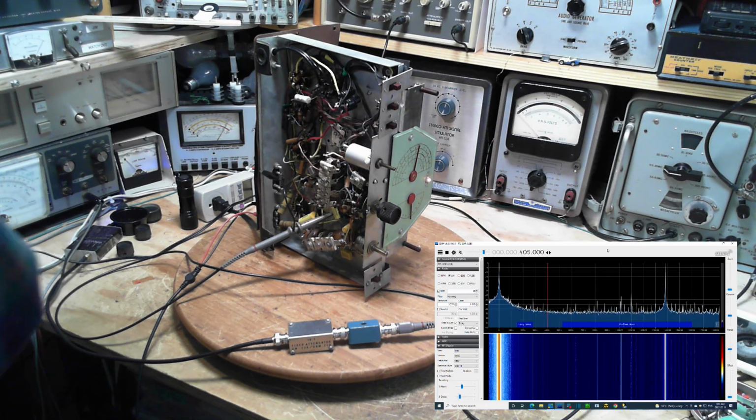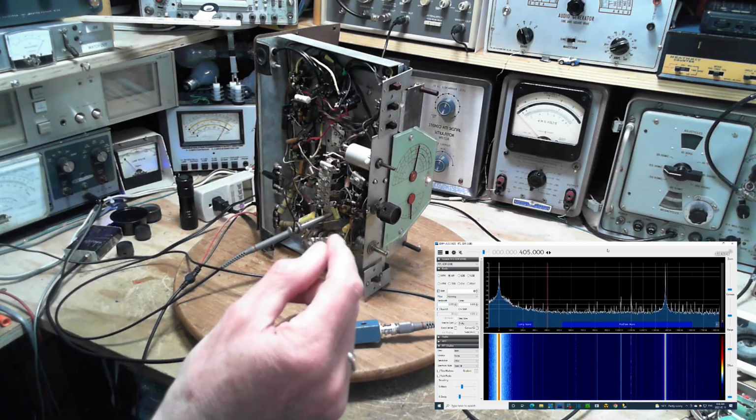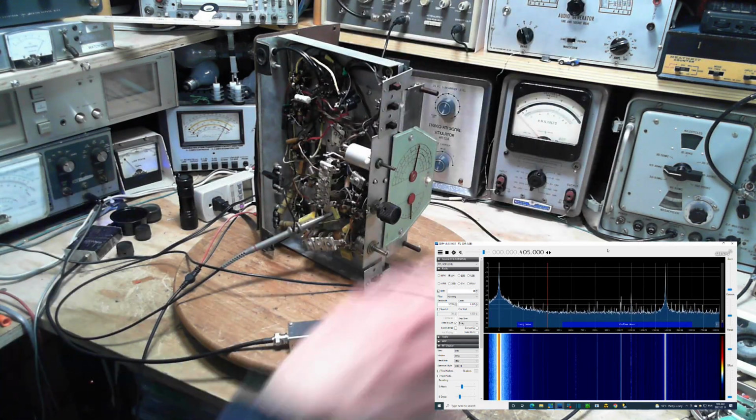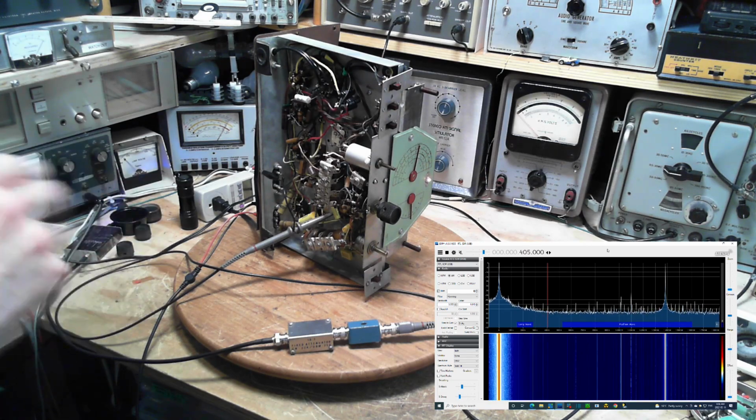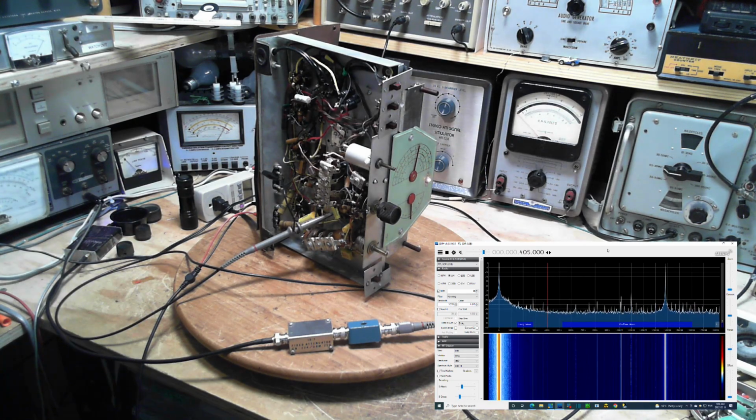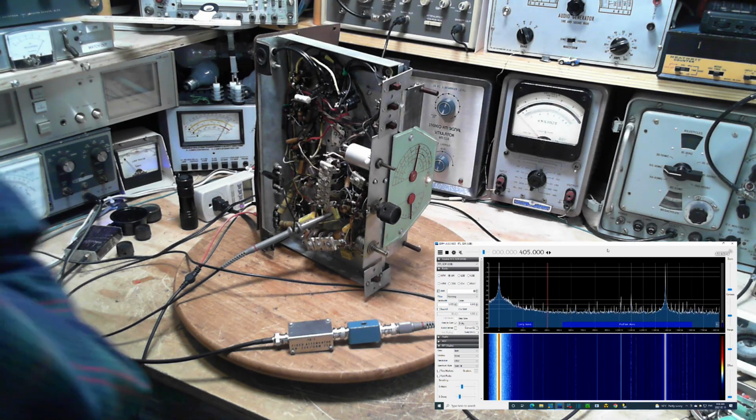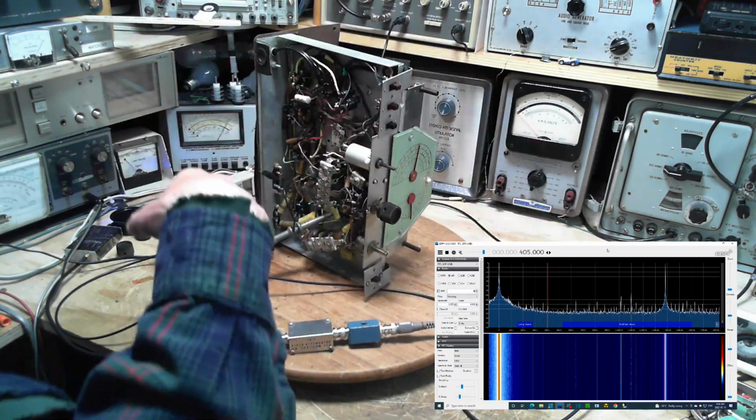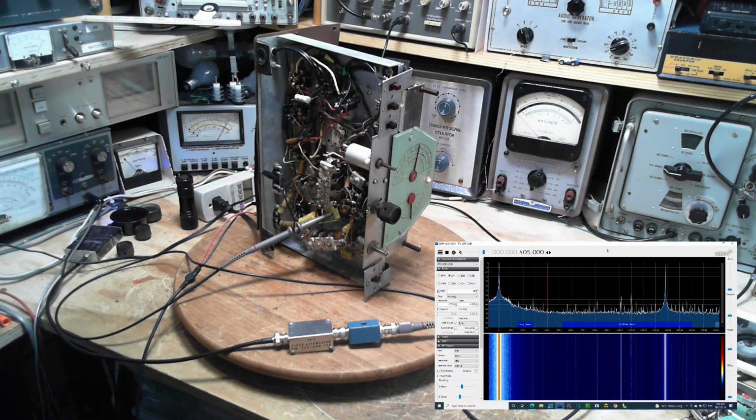It's an interesting question, because in my shortwave world, when I'm listening to radios, sometimes I have 2 or 3 radios running simultaneously, all on the same antenna. So if there are signals making it out of those radios and onto that antenna wire, it's going into all the other radios. It makes the scenario I'm looking at here just multiply it by the number of radios you've got going. Everybody hearing everybody. Now for sure you can hear local oscillators in other radios. If you have multiple radios going, one radio can pick up the local oscillator of the other one. And the antennas don't necessarily need to be connected together.